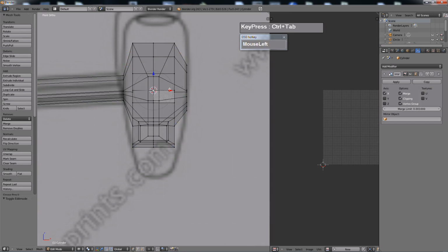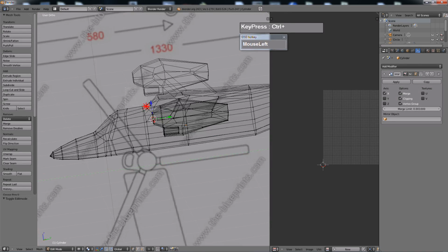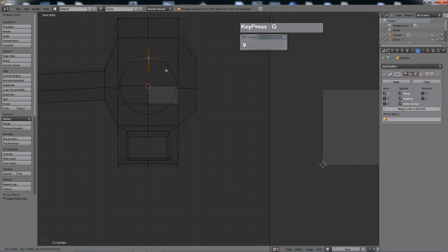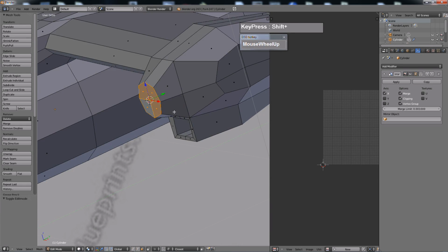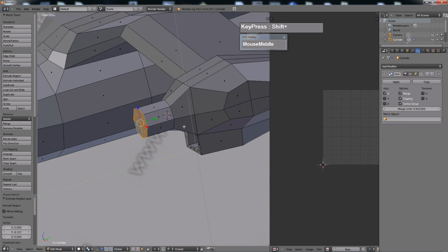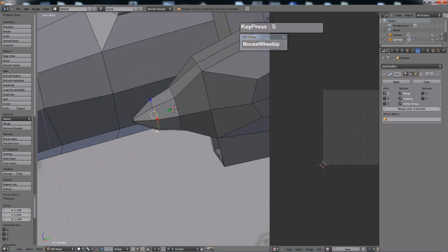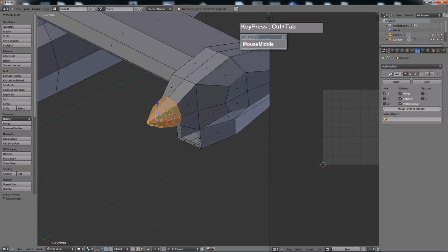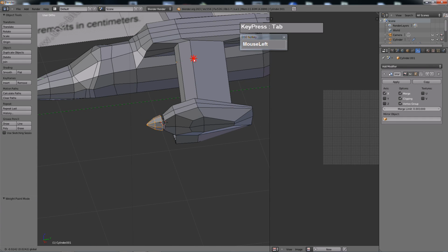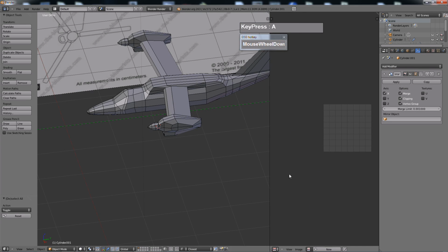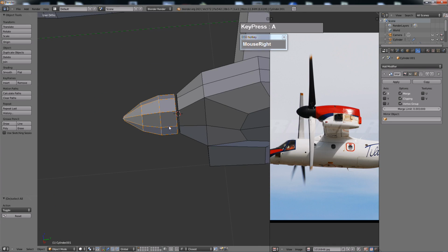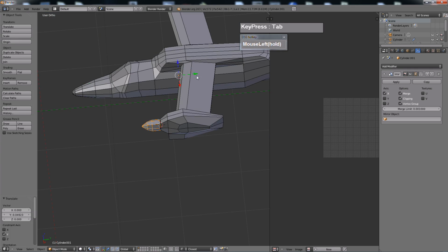Okay, so I actually brought in a circular mesh to be used as a guide to snap the mouth of this box to the circle guide. So once you finish using the circle guide, you can actually delete it. And then I've extruded a section of it, and then I scaled the points to form a cone. This will become a spinner, alright? And from the spinner, we will build the 3 fan blades.